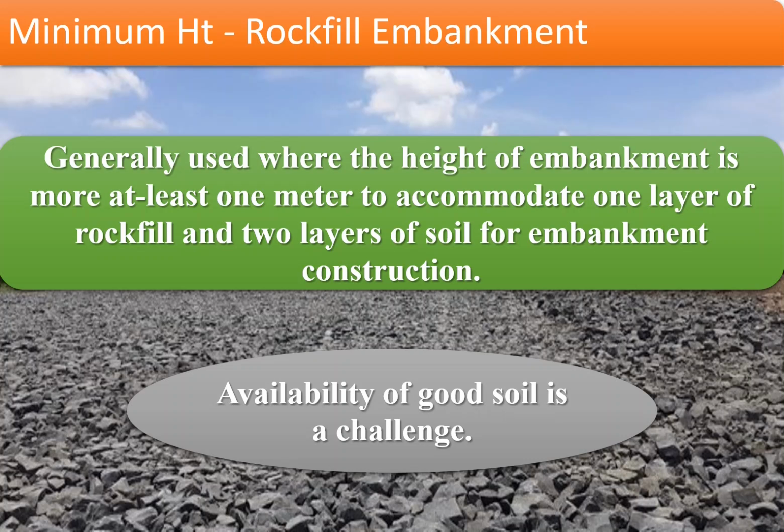Now, the minimum height one should have in order to go for a rockfill embankment: the minimum layer thickness of rockfill is 500 millimeters. So generally, for an embankment height of more than say 1 meter or 1.5 meters, rockfill can be adopted. But if the embankment height in total is 500 millimeters, then probably you will not be able to adopt the rockfill embankment.